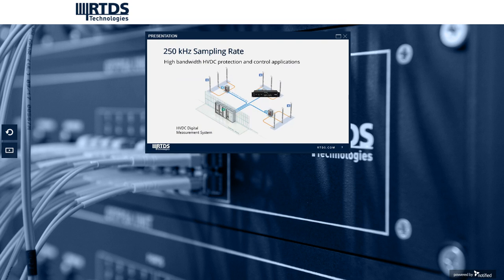250 kHz offers more than twice the speed of 96K. It is required by HVDC protection and control applications. For example, for HVDC traveling wave-based fault location, they usually sample at 250 kHz to 1 MHz sampling rates. So that's why we're developing 250K here.